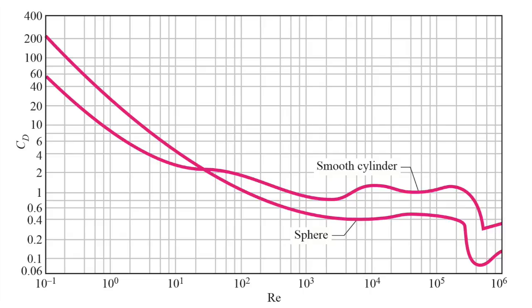This means that our tripwire had the effect of increasing drag on our cylinder at all three speeds, which is likely due to the fact that although flow separation was delayed, it was still likely separated far ahead on the cylinder than we had intended in order to reduce drag. Additionally, our baseline configuration's drag coefficient was well below what would be the theoretical drag coefficient for a smooth cylinder, though this may be due to our use of the flat plate approximation to calculate friction drag instead of a more accurate and complex method like CFD.